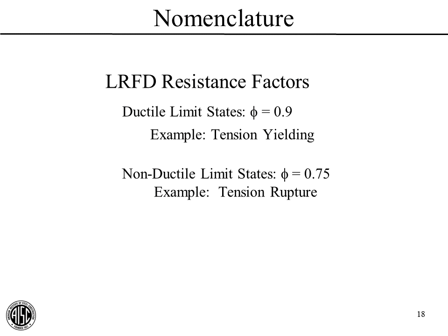Okay, we're going to be using load and resistance factor design for our entire webinar series. So let's talk about the resistance factors for a minute. The resistance factors are intended to account for inevitable uncertainties in the strength prediction. They are not there to account for design errors or construction errors.